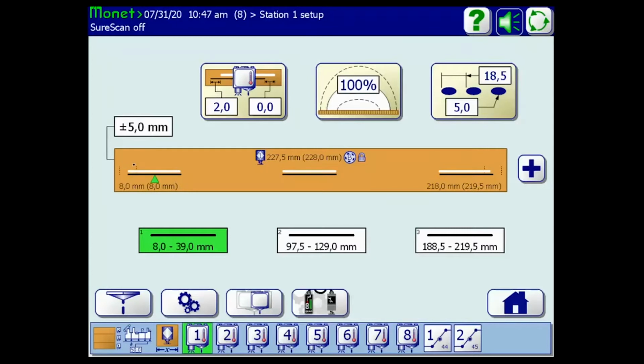It's actually 10 millimeters. It's actually a plus minus tolerance. So we know the glue is programmed to start at 8 millimeters here. That's where this black line starts from the lead edge of the panel. Because this is a plus minus tolerance, we're saying the start of that detected glue line can start up to 5 millimeters early from where I programmed it or 5 millimeters late. In other words, the overall window of opportunity here is actually 10 millimeters, plus minus 5 millimeters from the program start. Does that make sense? All right.